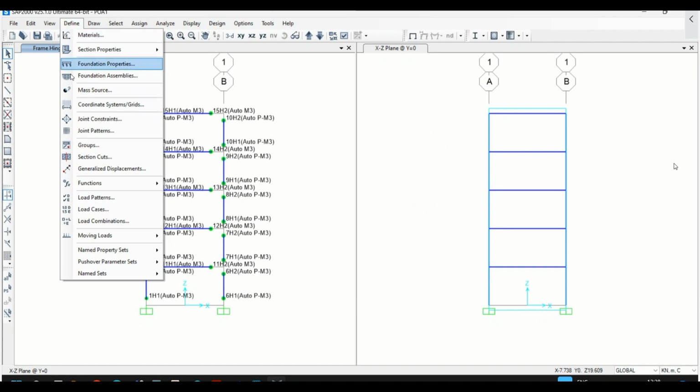Next, you can define a load pattern to apply the loads. It can be uniformly distributed in all stories, or you can also use an automatic lateral load type, for example, a quadratic distribution or triangular distribution, right? And you can use that pattern to apply the lateral push for the pushover analysis.